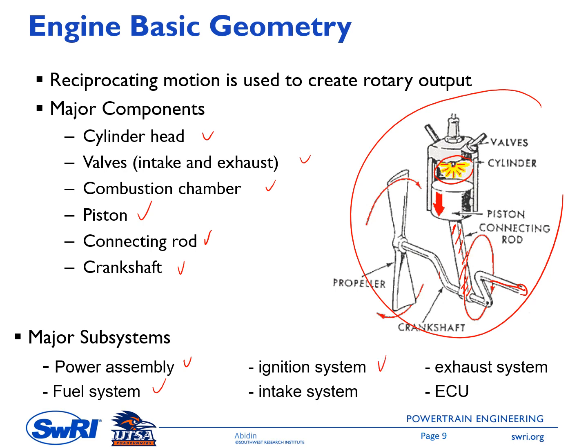We also have an ignition subsystem, so we have spark plug and then coil and so on. So we have an intake system, so we have intake port, intake runner, intake manifold. Similarly, we have an exhaust system, so we have exhaust runner, exhaust port, exhaust manifold, and ECU, electronic control unit. So this is kind of like the brain of the engine, so it controls everything.